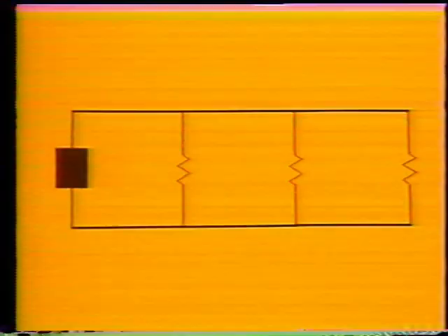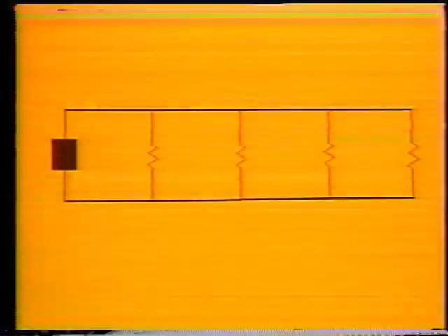Now, back in segment 2, we saw that the total current in a parallel circuit increases when branches are added. Since power is voltage times current, increasing the current also increases the power. This schematic will help you see how this works. This circuit is the one with 3 resistors that we've been using. This one has another resistor added to it. We've added another load in parallel. Now, the source voltage for each circuit is 5 volts.